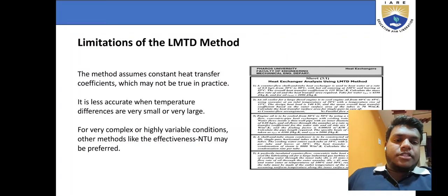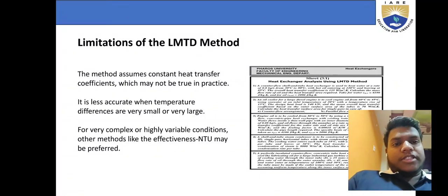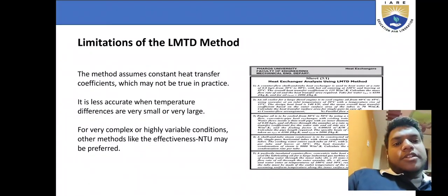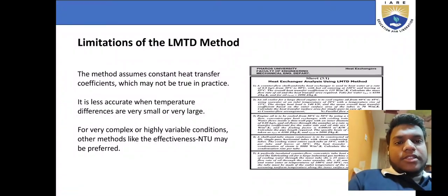Limitations of the LMTD method. The method assumes constant heat transfer coefficients, which may not be true in practice. It is less accurate when temperature differences are very small or very large. For very complex or highly variable conditions, other methods like the effectiveness NTU method may be preferred.